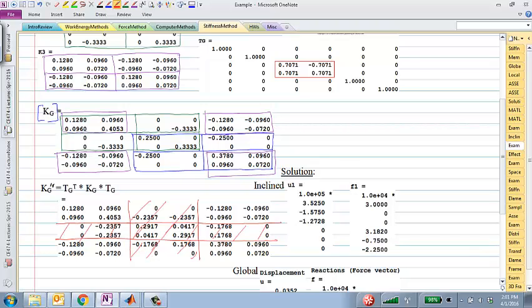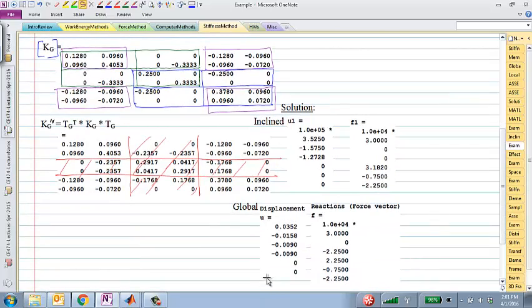Now using this, I can calculate the transformed displacement vector and the transformed force vector, convert it back to the global transformation vector. That's there. This u, as we just said, was equal to T times u double prime, and this f is equal to again transformation times f double prime.